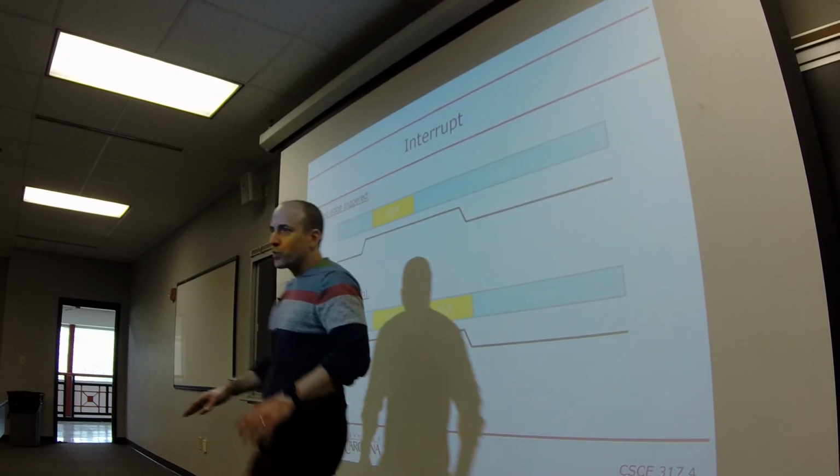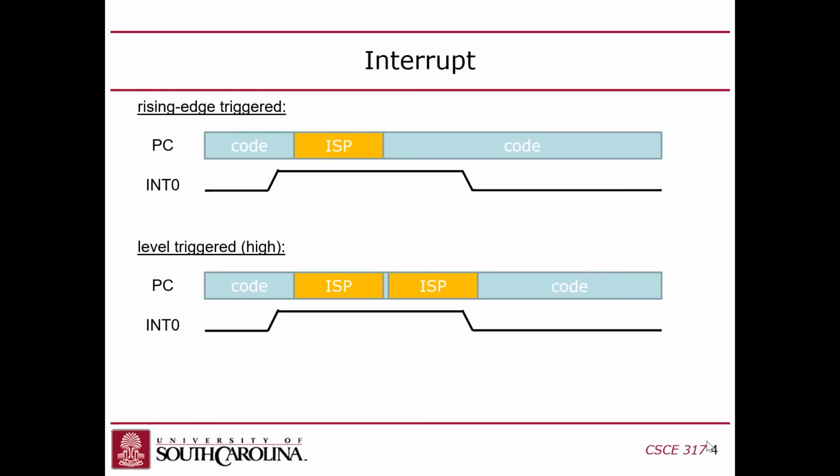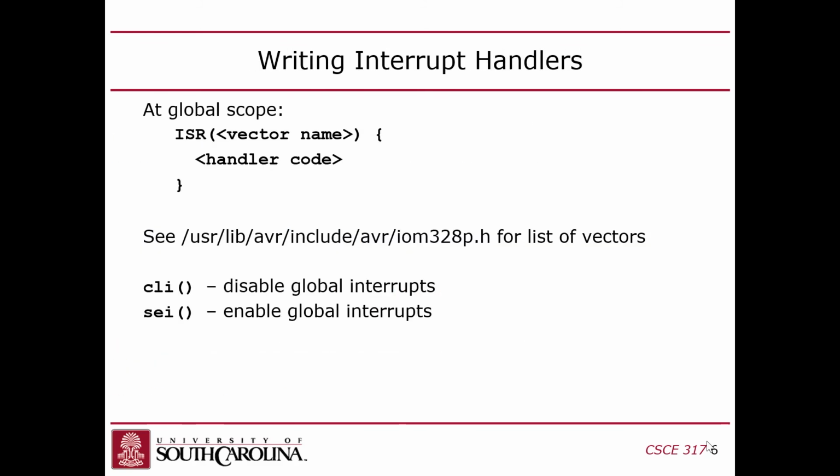So this is really what solves this problem that I was showing here, which is where you want to synchronize the interrupt with the chip's servicing of the interrupt. You want to make sure that while you're handling the interrupt, you do something that acknowledges the interrupt to the accelerometer, right? So that's the latch setting.